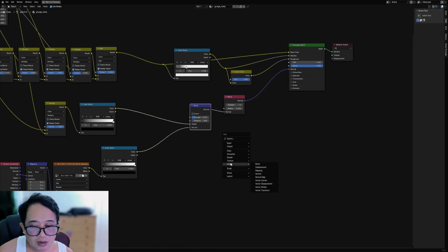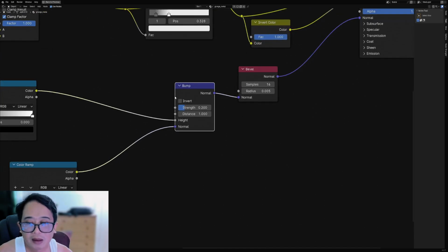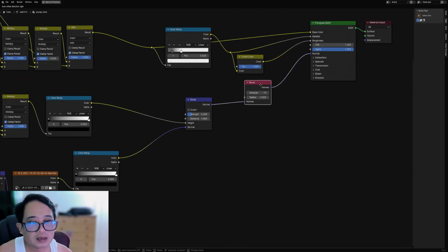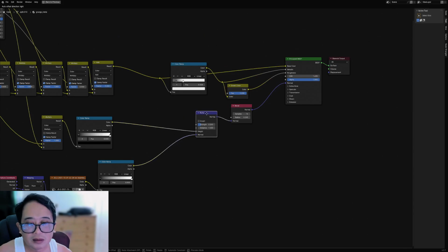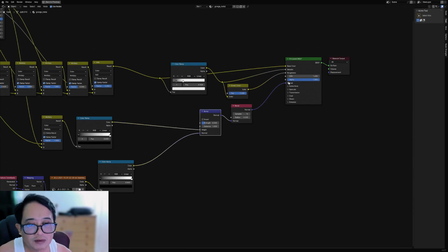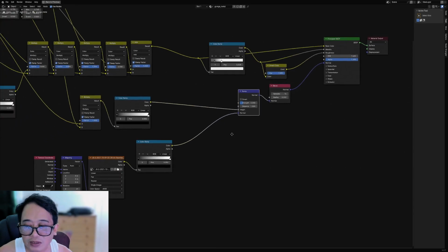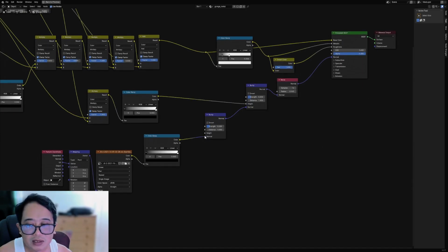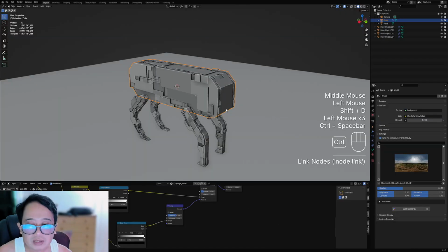From before, in order to add the effects of the normal information, you need to use Vector Math, but in the newer versions of Blender, all you need to do is attach them to the normal input of the last node that affects the normal of the BSDF shader. So bump, and set this to height. Let's use 6 for now.